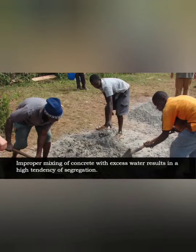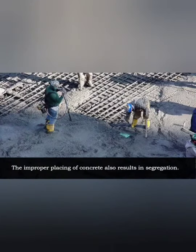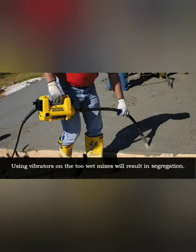Besides, improper mixing of concrete with excess water results in a high tendency of segregation. Improper placing of concrete also results in segregation. Using vibrators on too wet mixes will result in segregation.